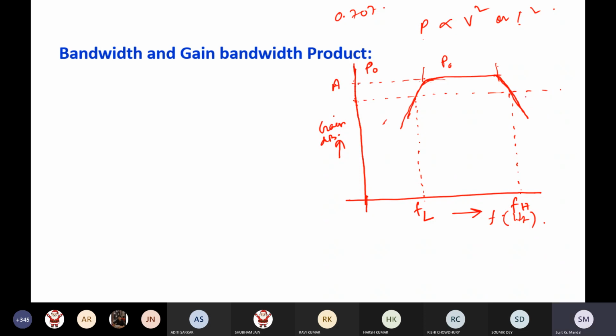That range of tolerance is generally defined by the 3 dB point, which is considered the cutoff point, also called the half power point. That means how much variation at maximum we can accept as the allowable range. This is the rule of thumb, and we take the half power point as the allowable range for the bandwidth. Clear? So that's why there are two cutoff frequencies.